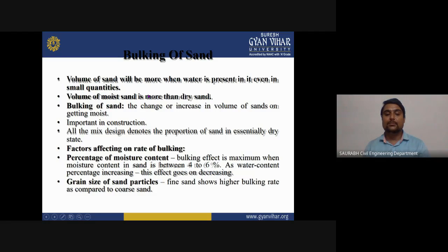Bulking effect is maximum when the moisture content in sand is between 4 to 6%. As the water percentage increases, this effect goes on decreasing. So you can understand this can also be harmful for the preparation of mortar and concrete.